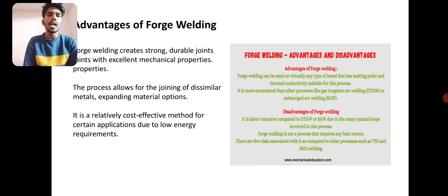And there are also advantages that forge welding has. Let me explain these advantages. The process allows joining dissimilar metals, expanding the material options. If you join by using forge welding, you can expand the range of metals which can be joined using heat. It is a relatively cost efficient method in certain applications due to the lower energy requirement. It also gives strong, durable joints and good mechanical properties. So these are the advantages of forge welding.